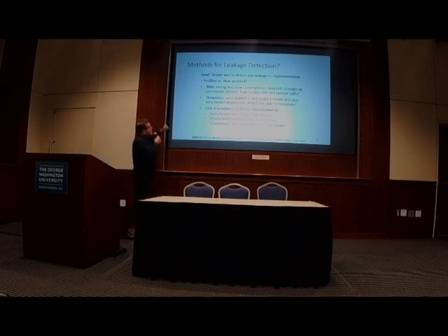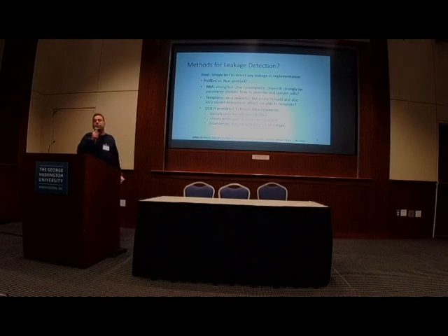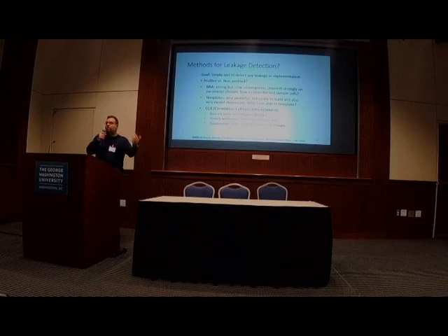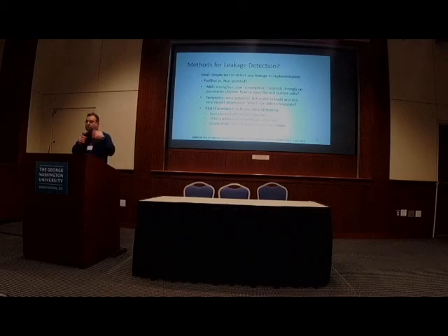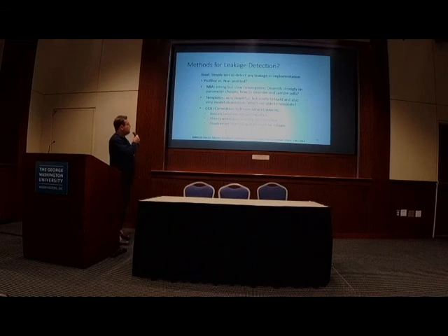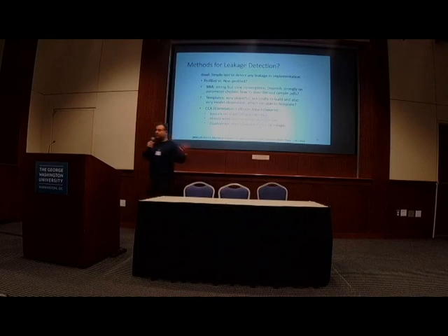Mutual information analysis has been used successfully. It's pretty strong. It gives you quite reliable results. It needs a lot of data to converge. That's the downside of MIA. Template building is another way of detecting leakage. Just think about template attacks: you build profiles and templates and then verify. But you need to build the templates first. And then collision attacks. It's a self-profiling attack, already used. The disadvantage is that it does not work for single bit leaks, so it has limitations.